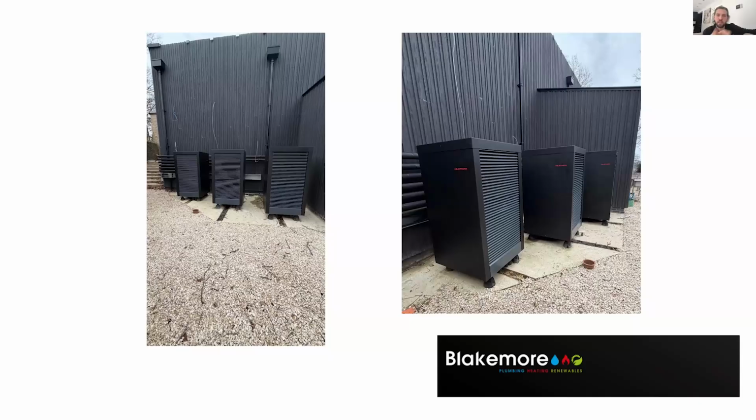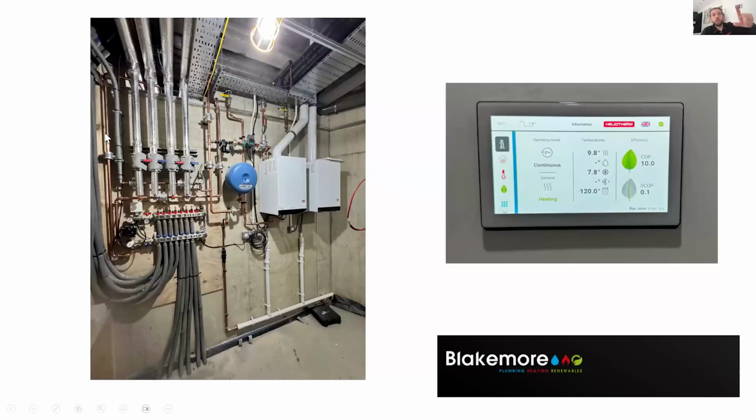So we've gone with an 850 litre buffer. I don't know if there are any more slides that we can move to with this plant room and whatnot, but 850 litre buffer. So this is the hybrid bit for the pool. There's a gas boiler that's going to the pool there, an expansion valve. We've used Kingspan throughout, the 20 mil insulation all there.